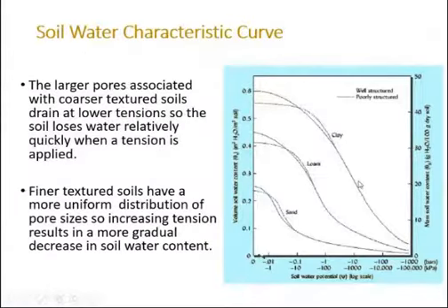Something that you have to keep in mind is that every texture has a different retention curve. Why? Because it depends on the soil texture itself and on the pore size distribution in each soil texture. For example, a sandy soil has larger pore spaces, so when you apply water, the water can drain very fast from the soil.